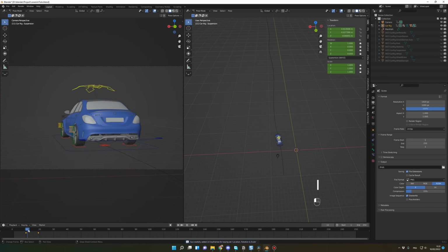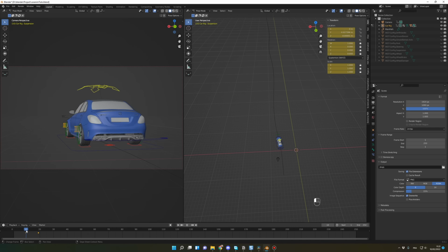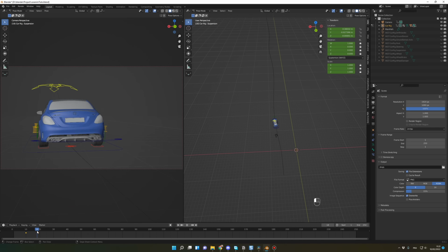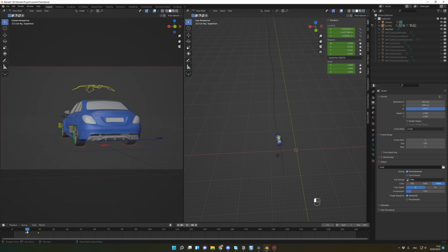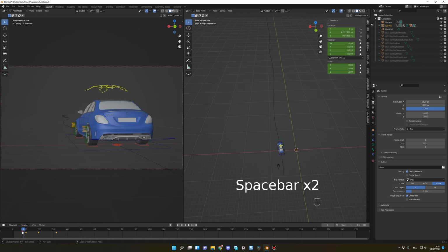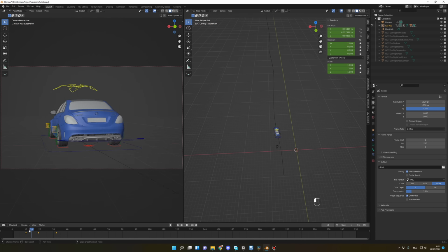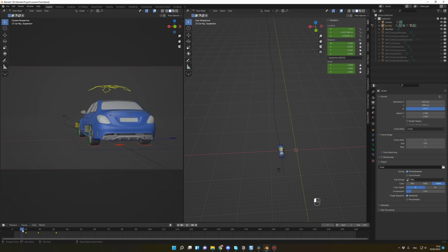So if you check the animation now, as you can see, my car is simulating the fact that the centrifugal force is applied to it. Okay, perfect. And let's say that it should become normal just there. So item again, X 0 to go back to the origin, and I. So now you see, I add some realism to my animation because I have applied the centrifugal force.